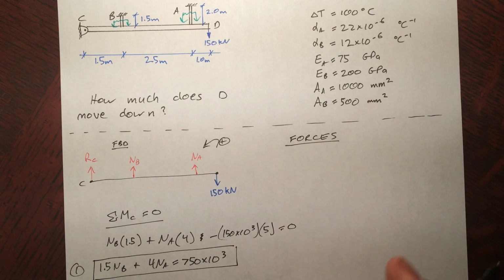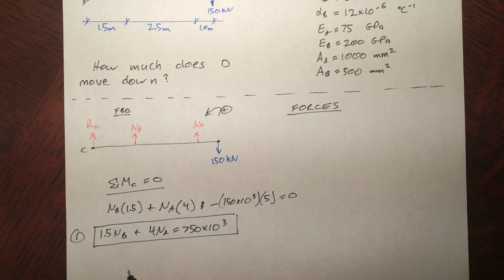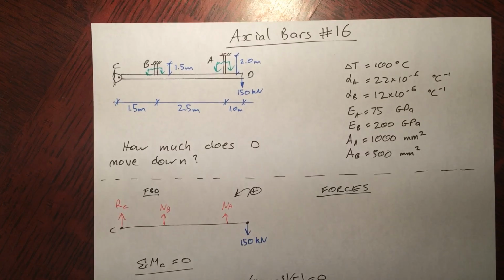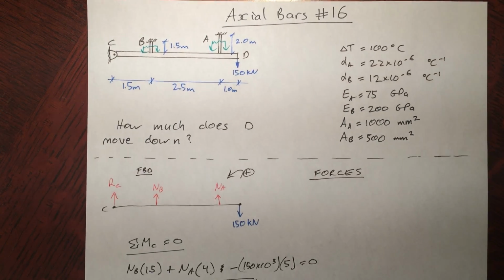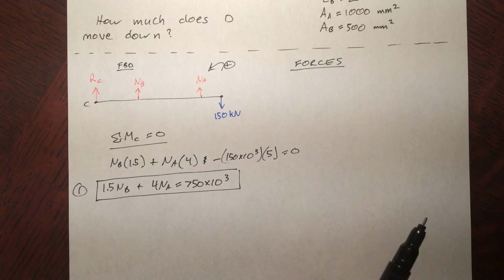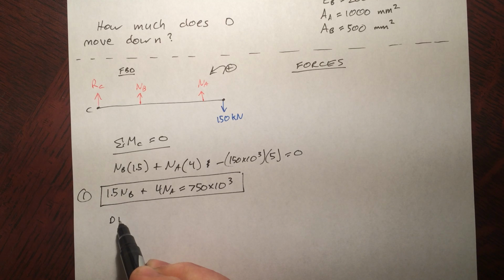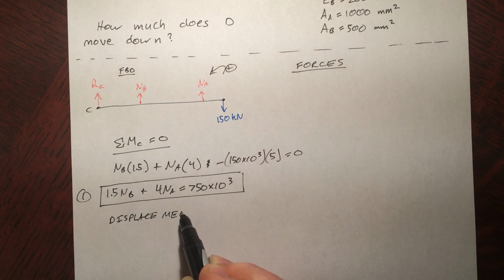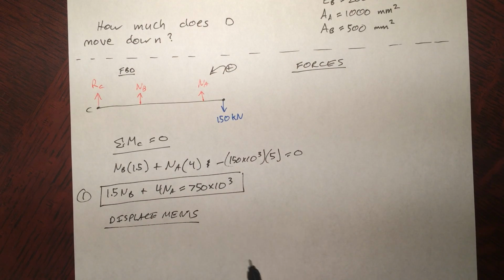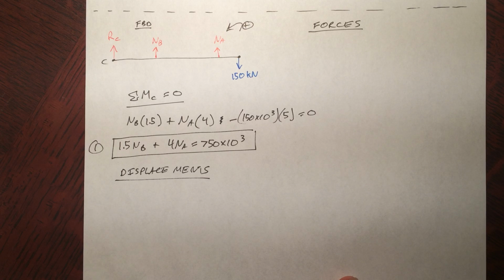It's the result of taking a look at the forces. So we can see it's statically indeterminate. We have two unknowns, and we have no other way to find any of the other unknowns by just looking at forces, moments, that type of thing. So we move into displacements. We need to look at the geometry of displacement of this quite closely.